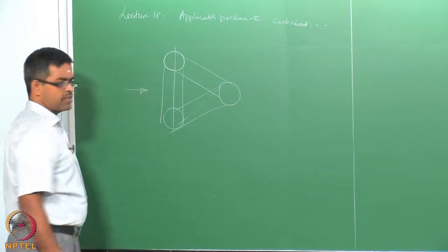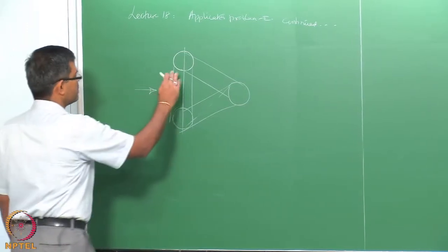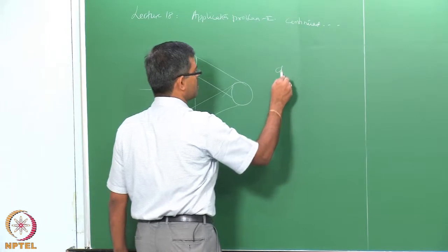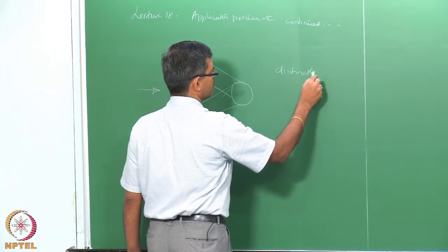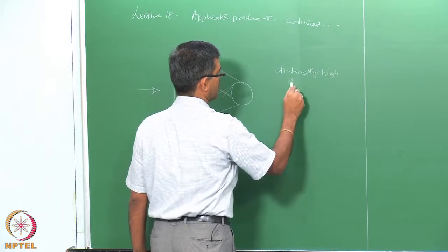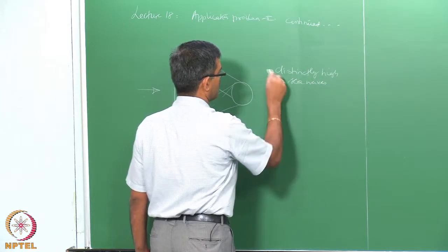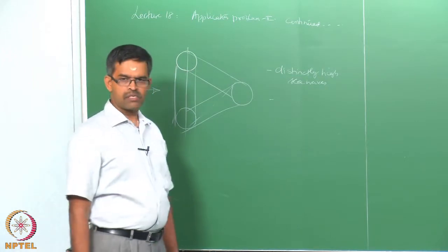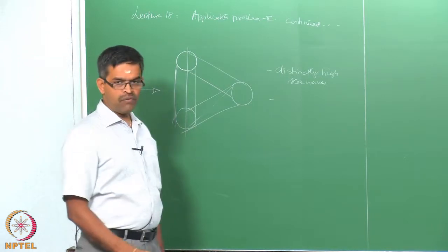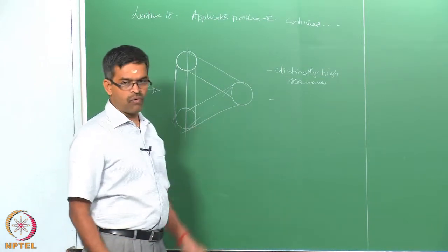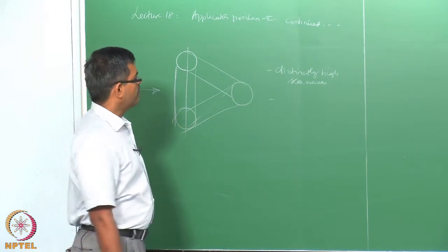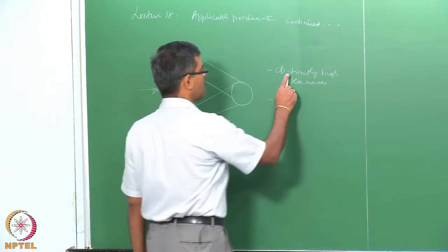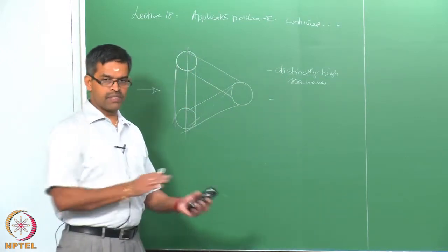where the predominant wave direction is along the surge axis. It is subjected to distinctly high sea waves, which we know how to generate using the modification suggested by Mitchell 1999, and we have a modified PM spectrum based on which you can generate the forces arising from the hydrodynamic effects caused by the distinctly high sea waves, because you have to qualify a wave as a distinctly high sea wave by comparing the wave elevation with the preceding and successive wave history.